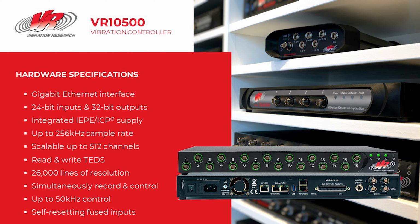Some of the colors that are featured on the front of the 9500 and 10500 are red, yellow, and green. Green is good when we're providing that IEPE signal to the front inputs. That means we are providing power to an accelerometer and it is getting good feedback, so it's a green LED status ring around the front of the unit.